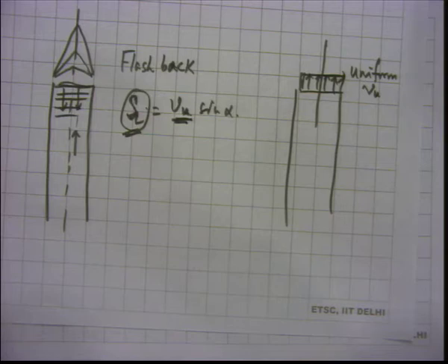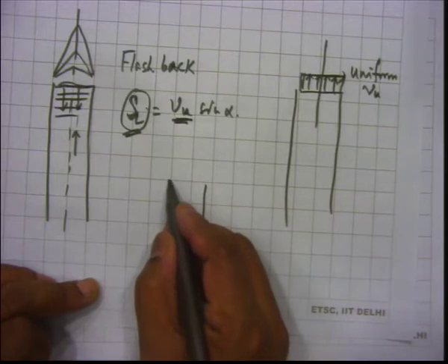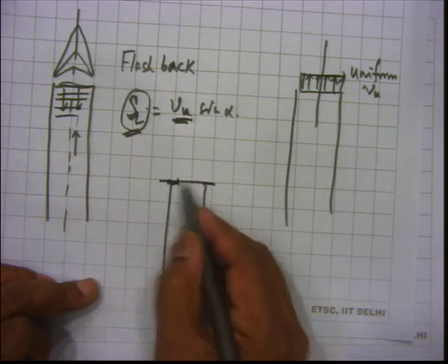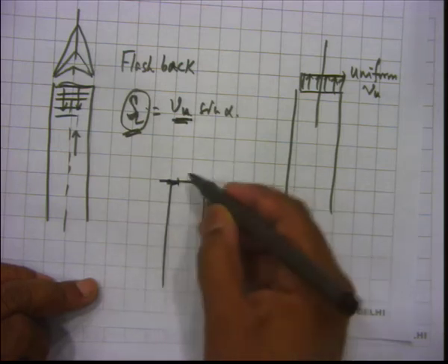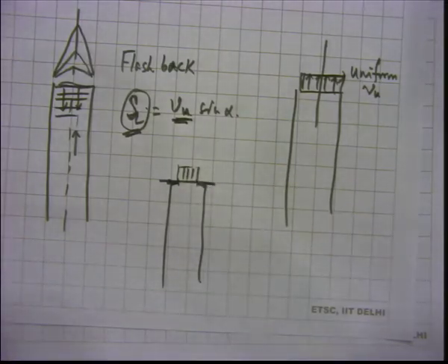You can't get that with a tube, because then it will tend to give you a more parabolic, more rounded velocity profile. If, instead, at the top of the tube you place an orifice with a sharp edge, then that tends to produce a more uniform velocity profile. So, there is a particular orifice design which can give you a more uniform velocity profile, and then that will tend to give you a sharp cone. But of course, most of the time that is not the case.